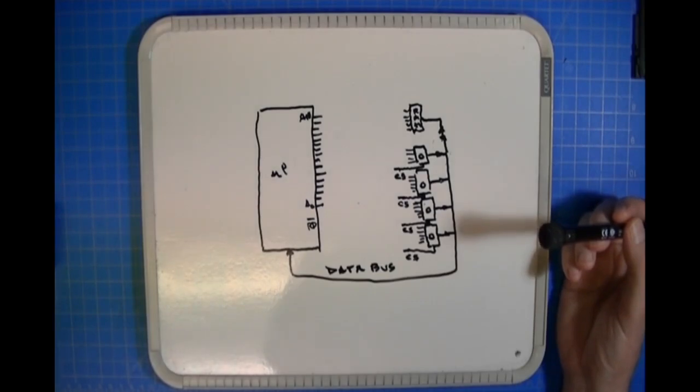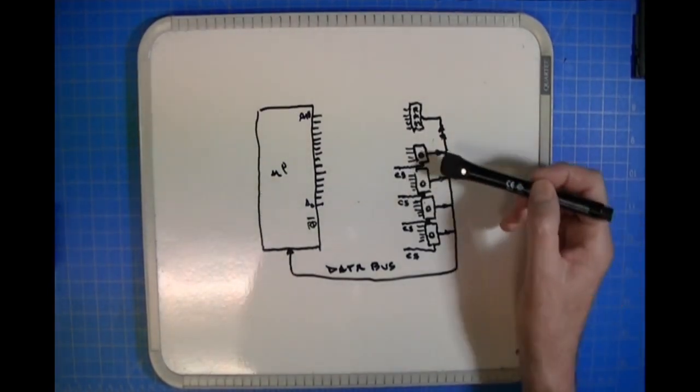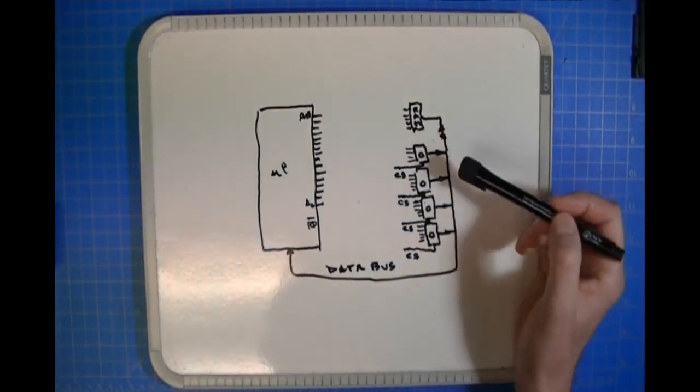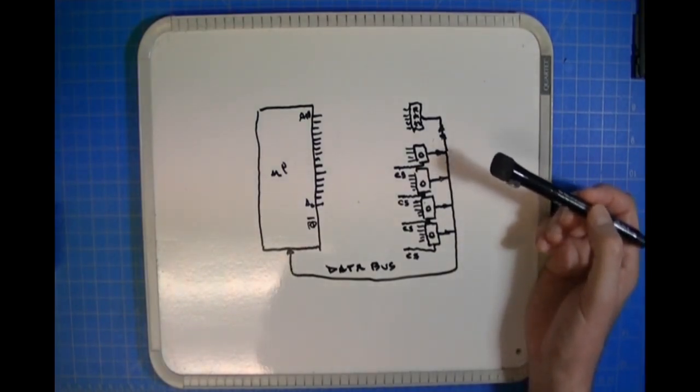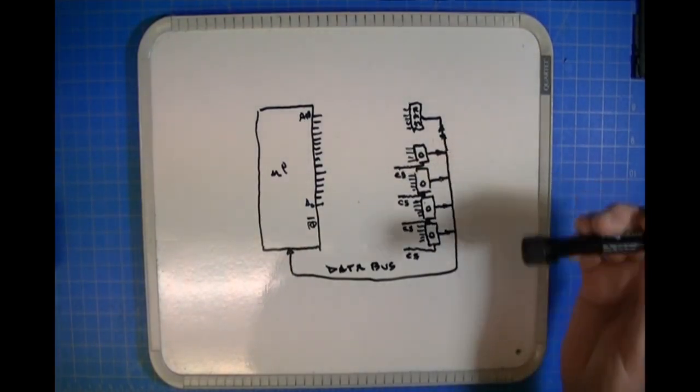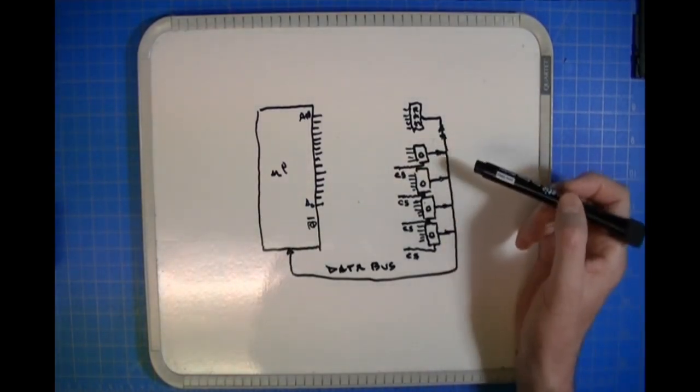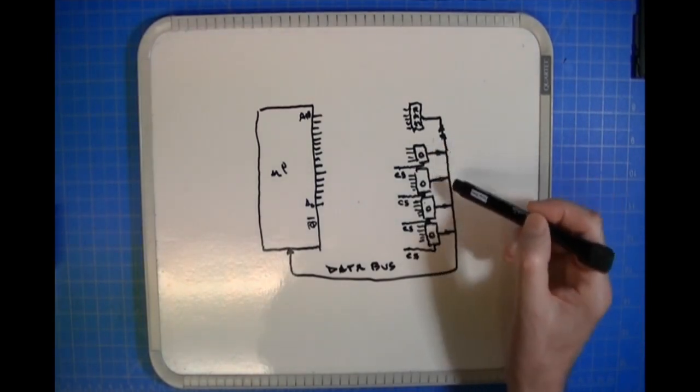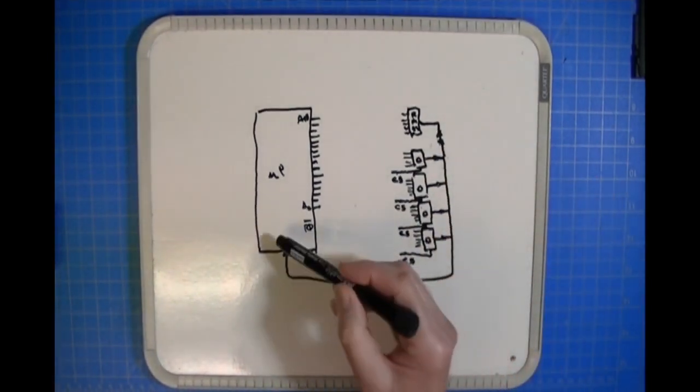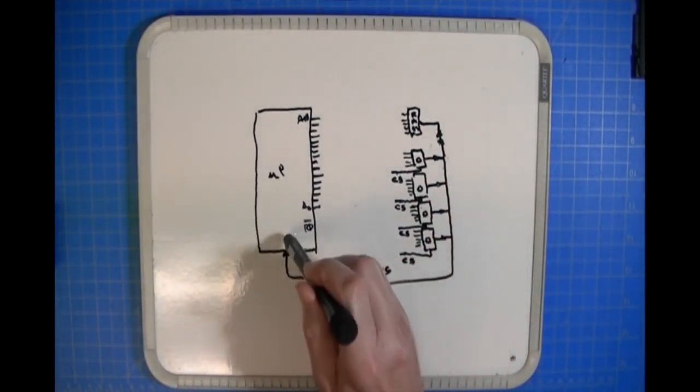That individual byte, once it is selected, will pass out of the data lines on the EPROM, which I've shown here. I know I didn't label them data lines because this wasn't supposed to be a course in microprocessors. The data will flow out of the EPROM and be read by the microprocessor right over here.